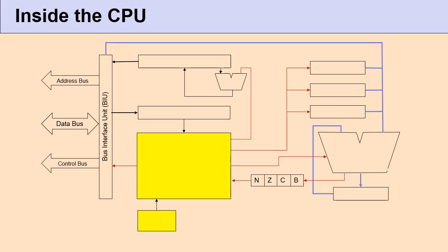It's like the heartbeat. At every cycle, it goes up and down, and during every cycle, the CPU carries out one action in the instruction cycle. So, the faster the clock, usually the more actions will happen in the CPU. Not always, but usually a CPU running at a faster clock will run faster. There are other things that also affect CPU performance, which we will not discuss right now.